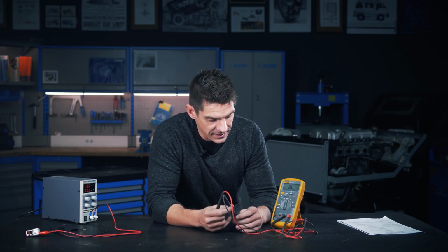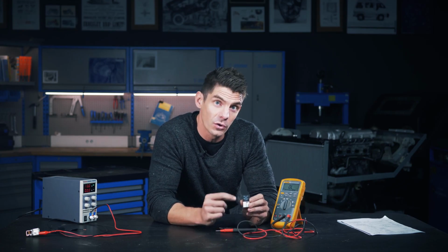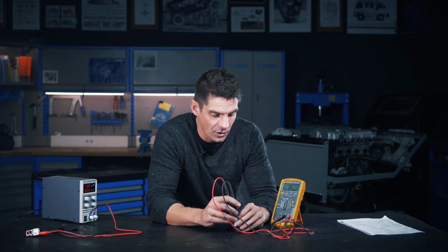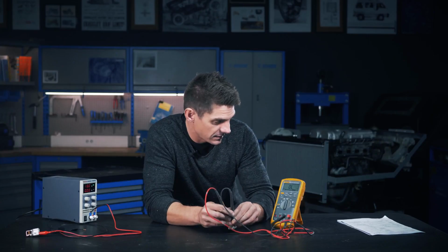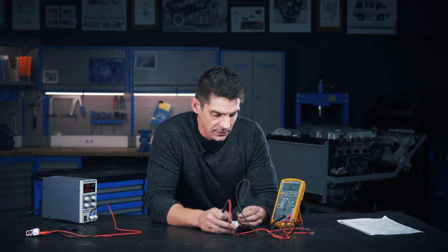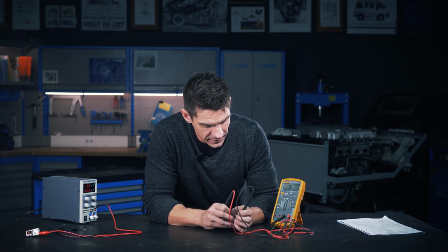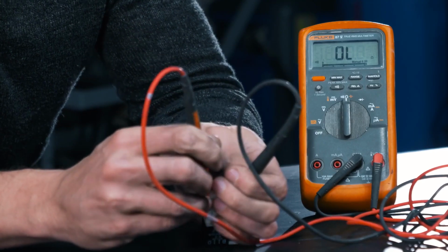So, having tested that, we can now test our high current side. We know this is an NO, normally open relay, so we expect to have an open circuit here. We don't expect to see a resistance across here. Let's see what we've got. It stays OL. As I bumble around here, you could probably do this in a more elegant way. But we expect across this output side to find an open circuit, which we do.